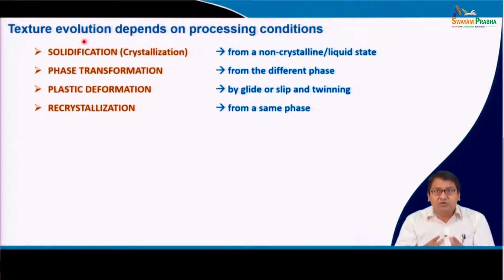Therefore, there is always a preferential texture that is developed during the solidification process. In order to obtain a solidified polycrystalline material with a weaker texture or a near random texture, there is a need to engineer the material to obtain that.